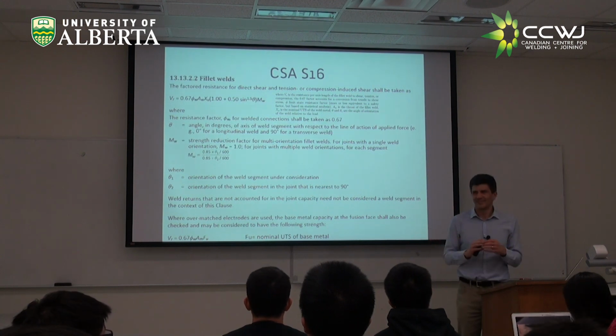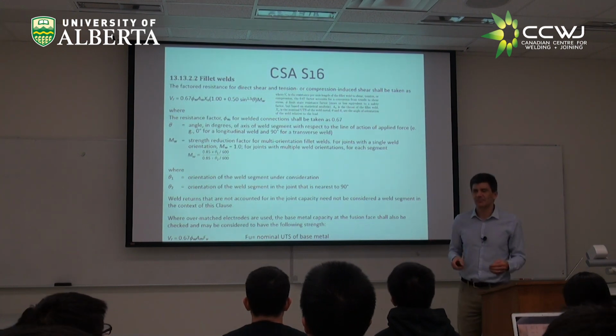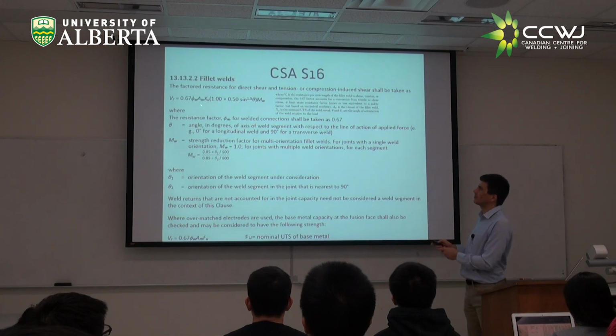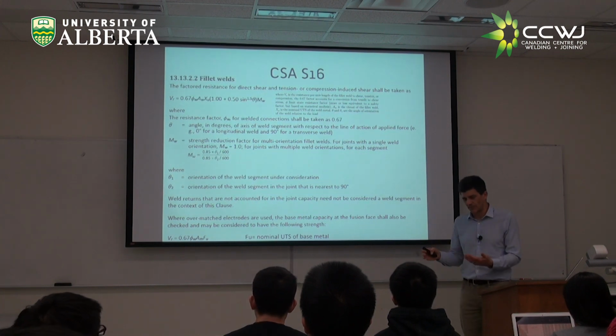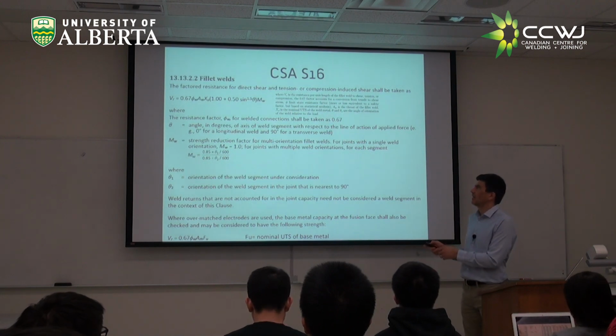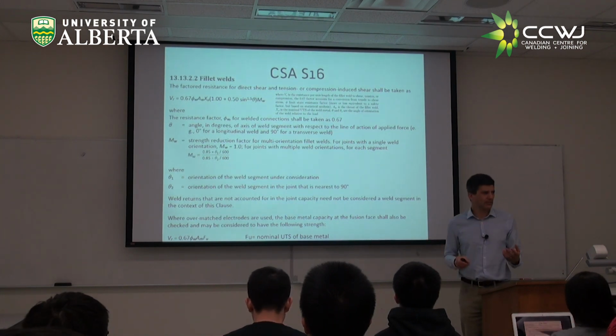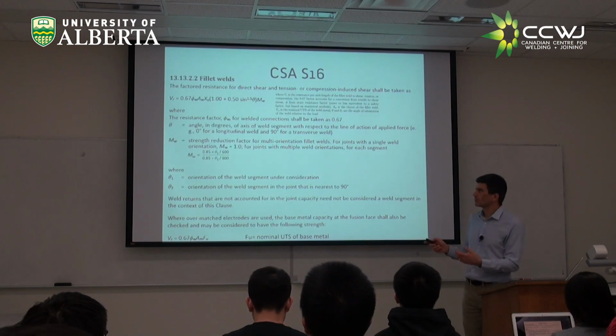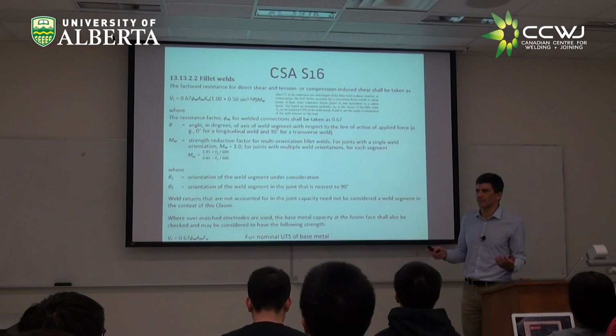In the end, the number is the same. So what I can tell you is this is based on lots of statistics in which they welded with all types of electrodes, all plates, much of that done in this university. But for you, in your exam and in your professional life, you put a 0.67 there, which is more or less what the Americans do.